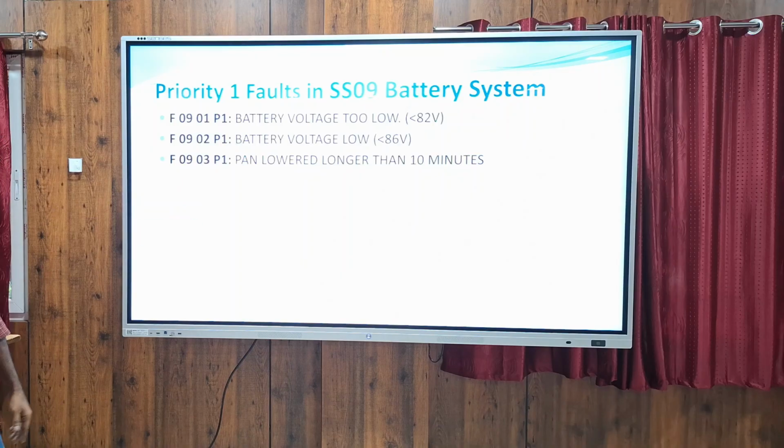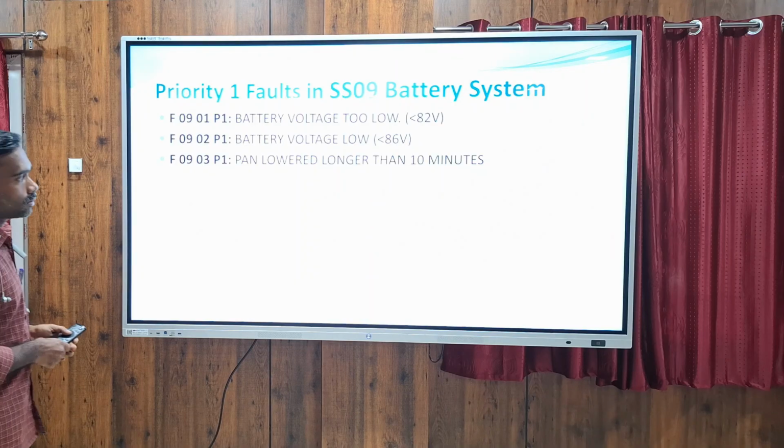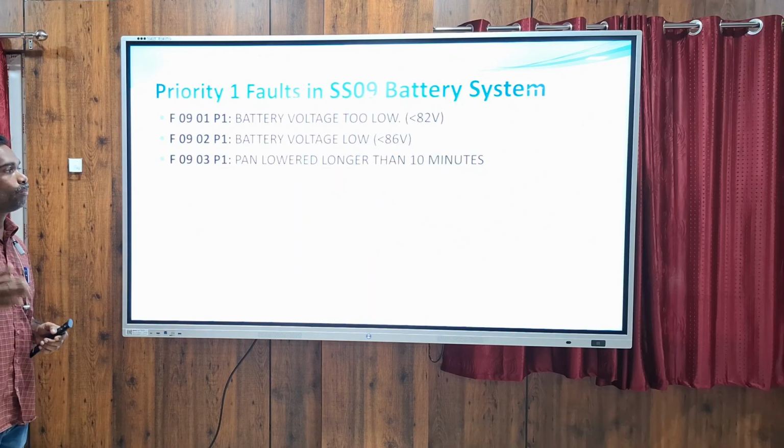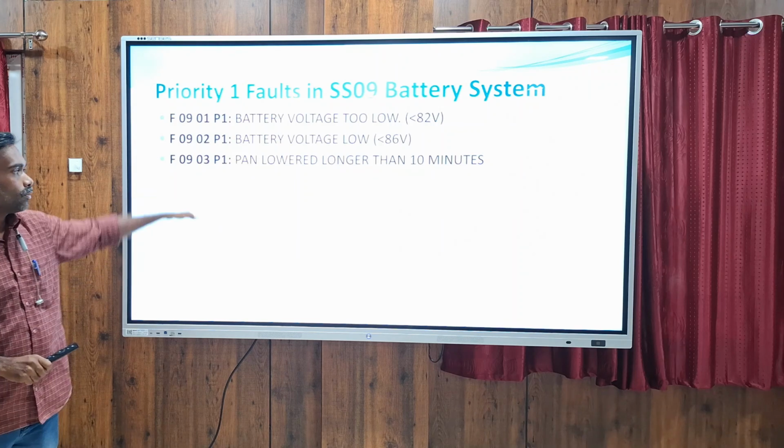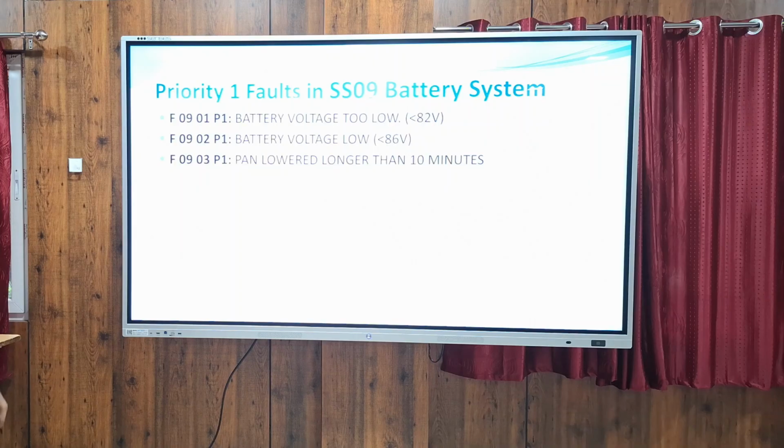Then Pantograph lowered longer than 10 minutes. If after switching on the BL key in driver mode the pantograph is not raised, and if more than 10 minutes have gone, then VCU will shut down the system into sleep mode for saving. So that is Pantograph lowered longer than 10 minutes.